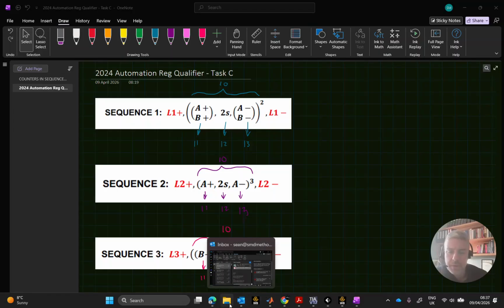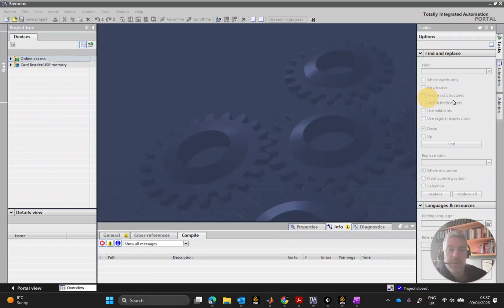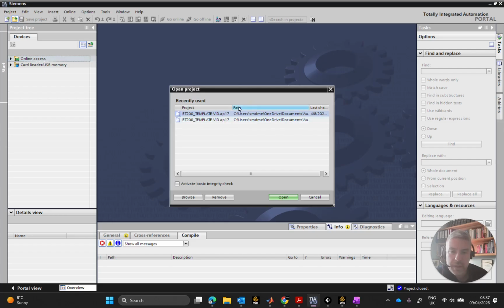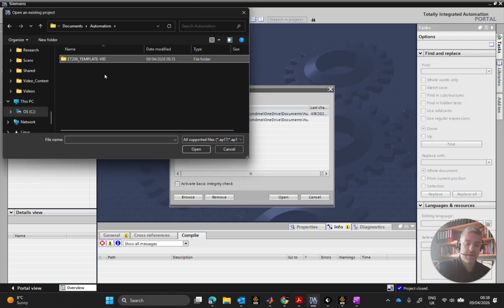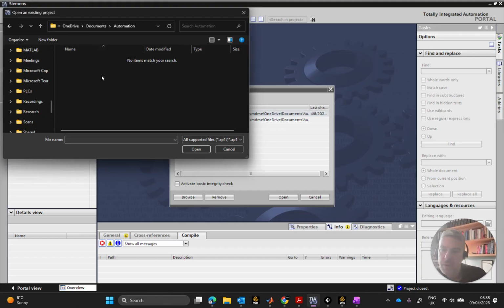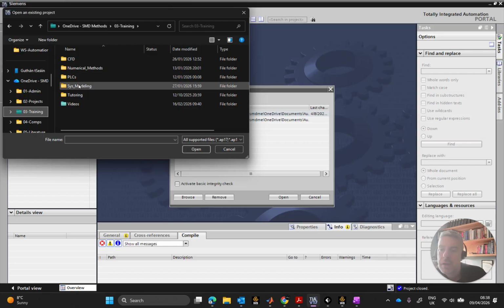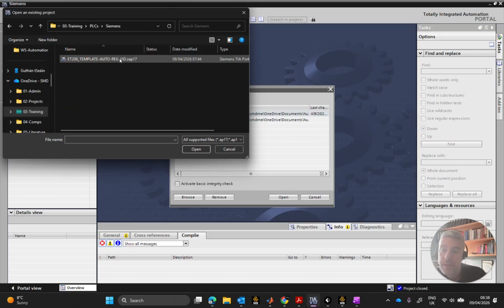Okay, now what we're going to do is go on into TIA here. And I'm going to pull this controls back over to here. I'm going to open up the template file that I created in another set of videos in this playlist. I have archived them into a single location. So if I go ahead and open up, let's browse here for automation. This was the one that I created. I'm going to delete that out. That was the one that I did archive. So I'm just going to open this up from the archive, which is in training, PLC, Siemens, and there's the archive, the ZAP file. Let's open that up.